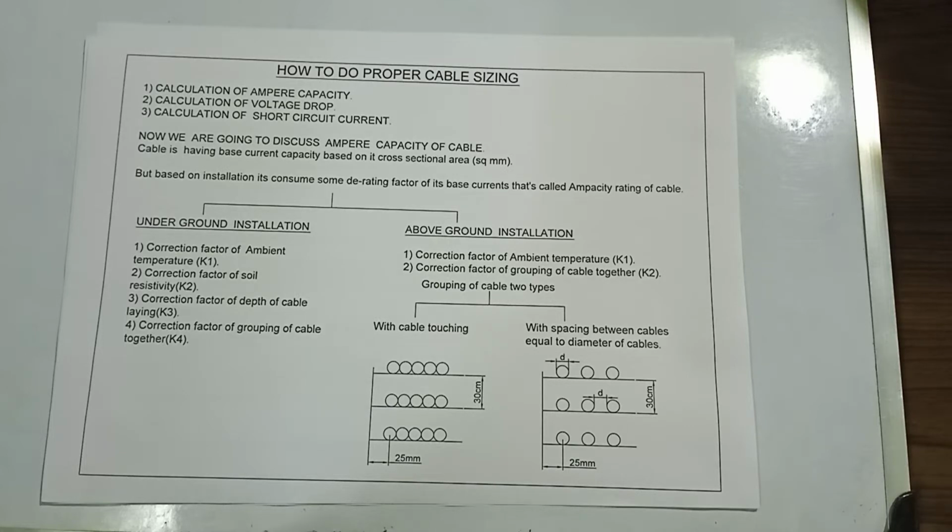Today I am going to discuss how to do proper cable sizing. There are three criteria for sizing of cable: calculation of ampere capacity, calculation of voltage drop, and calculation of short circuit current.